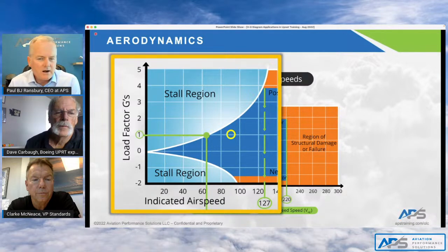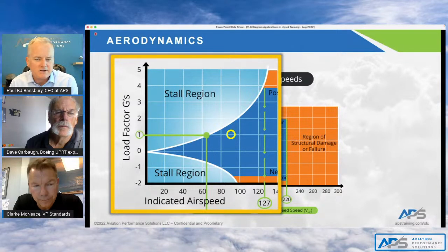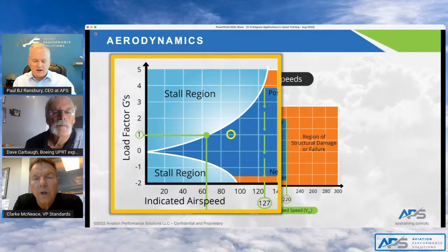So we're now in our general aviation airplane that's represented here. We're on approach at 90 knots. That's the appropriate speed. We don't want to be faster because of stabilized approach criteria. We don't want to be slower because of stall margin away from the 1G stall. And there we are. Why don't you take us through a scenario that could be useful to everybody at the event here today?